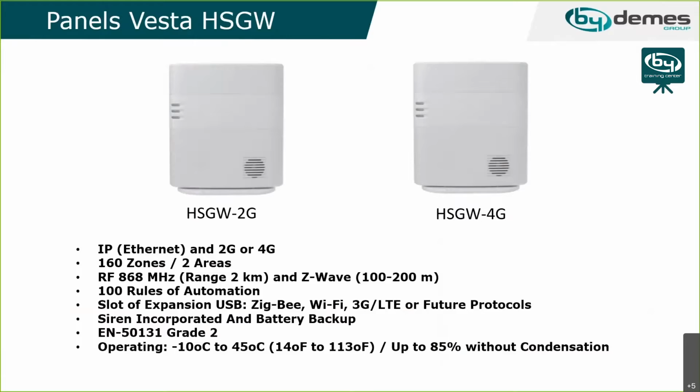Also, the panel incorporates a siren and a battery backup. The battery backup has around 8 hours of backup. As I said before, these panels can be connected to central monitoring stations because they comply with grade 2.